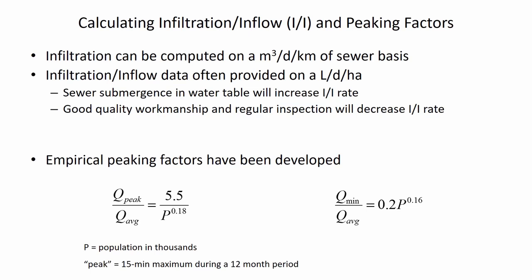And it's also partly due to the geographic diversity. If you have the water all going towards some central sewer plant in a big city, it takes a long time to travel there, and that dissipates the peaks. If we think about a big city like Columbus, Ohio, the sewage that's generated on the far northern edge of Columbus takes several hours to travel down to the treatment plant, compared to a smaller town with a centralized wastewater collection network, where the travel time is going to be less.